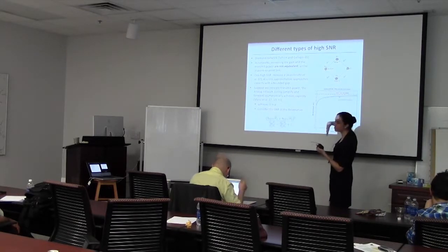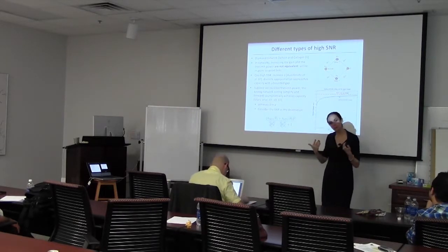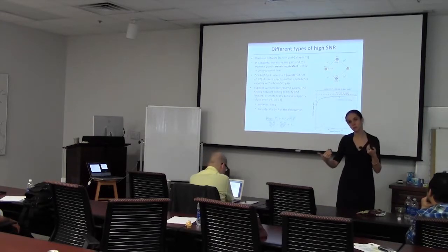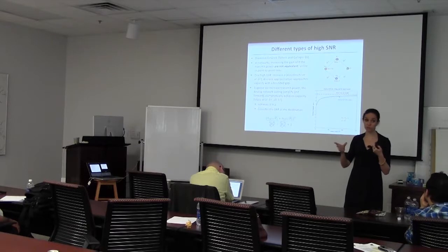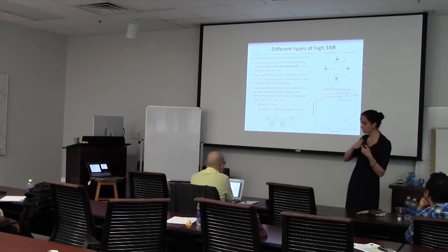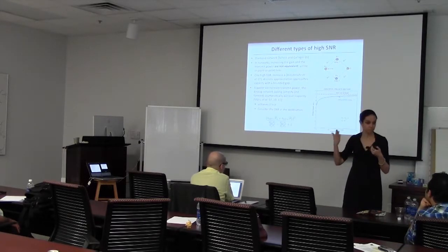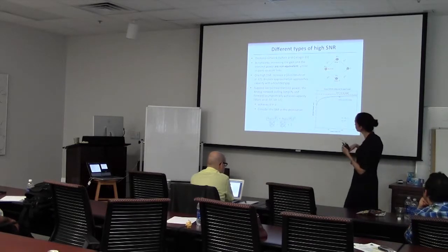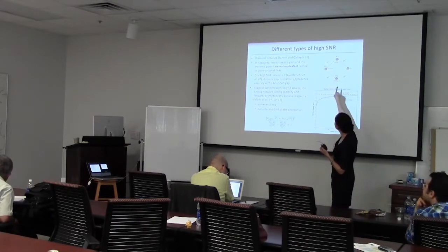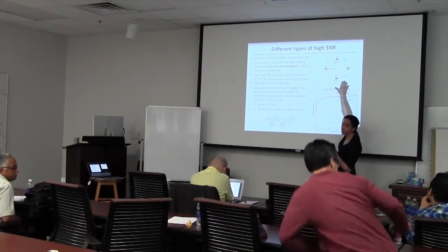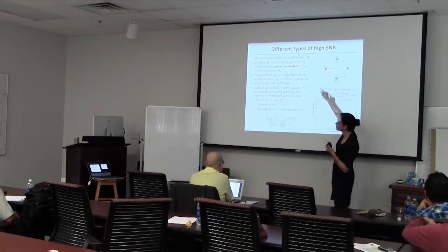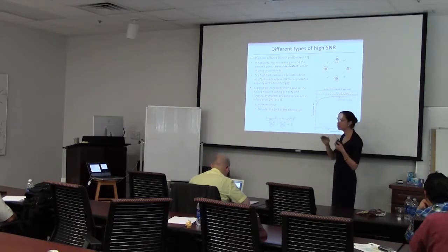And there's a bounded gap away from capacity, but it's a bounded gap that grows with the size of the network, and it's also a bounded gap of half a bit per degree of freedom, so per second per hertz. So as your bandwidth goes up, so does the gap. Okay. Suppose instead, if I'm in this network, that I keep the A's constant and I bump up the source power, not touching the noise in either case.